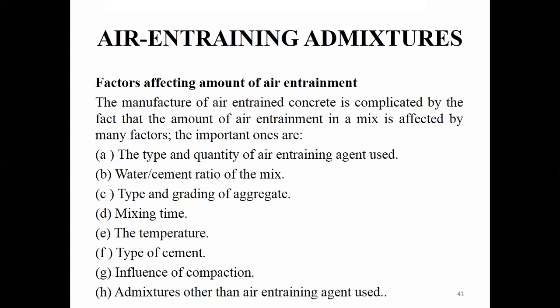Next we are going to discuss the water cement ratio. For water cement ratio we are considering three different cases: low water cement ratio, intermediate water cement ratio, and higher water cement ratio. Whenever you are adding a low water cement ratio to the concrete mix subjected to air entraining admixtures, the slump value will not be high. Whenever you are using low water cement ratio, there will be a lesser amount of air voids.